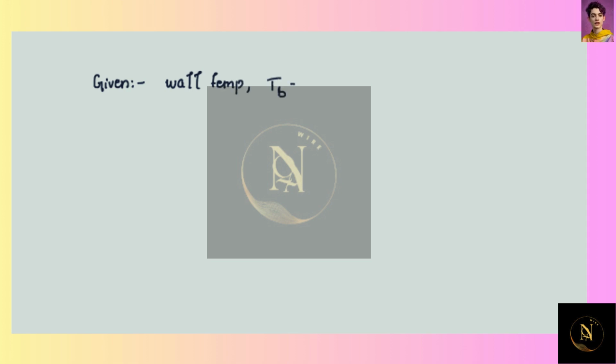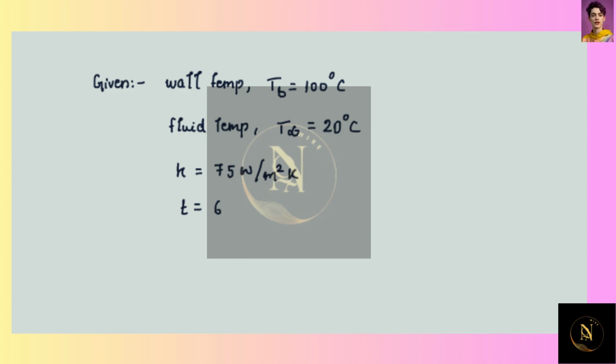Here in this question we are given wall temperature T_b is equal to 100 degrees Celsius. The fluid temperature T infinity is equal to 20 degrees Celsius. Heat transfer coefficient h is equal to 75 watt per meter square Kelvin. Fin thickness is given, which is 6 mm, and length L is given, which is 20 mm.